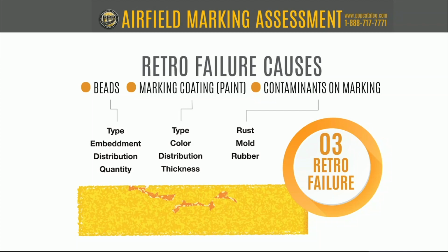The problem is if you use these for pavement markings, you're going to have a thick center and lighter edges. We talked about this earlier. I mentioned it in the bead part. What's happening is that the outer edge of those lines is oftentimes not thick enough paint to retain those beads properly, or to get the embedment for proper retroreflectivity. So that's something that you really have to watch for.